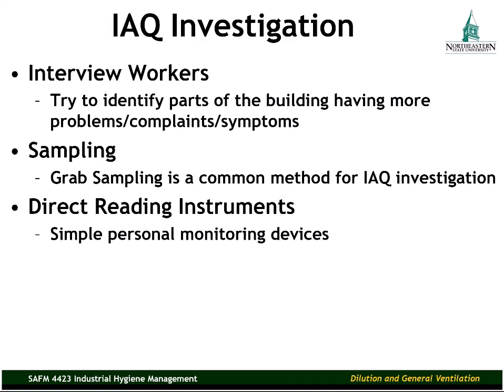And it's also going to test for carbon monoxide, which, again, it's probably good to take CO readings, carbon monoxide readings also, because that could be a problem. Maybe something's not vented properly. If it's a gas-fired furnace in a building and it's not vented properly, there could be carbon monoxide being spewed throughout the ductwork. That's a potential problem. Then the fourth gas most commonly tested with a personal monitoring device would be your oxygen level, and that would certainly be of interest also.